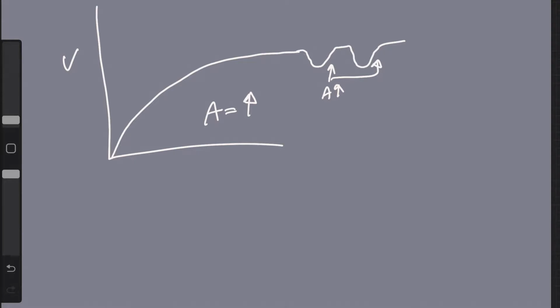Now when the battery is dropping, it's such a small amount of current that it doesn't equal the amount going back in. So each one of these ripples is basically an error, in that it isn't really a true amount of current that we want to measure anyway. And so the energy that we're going to measure is the current times the time. This means that the amp hours, which is the unit that we're measuring, is going to increase all the time, even though the battery is full, because it's just going to sit here and cycle continuously as long as we have the charger plugged in.